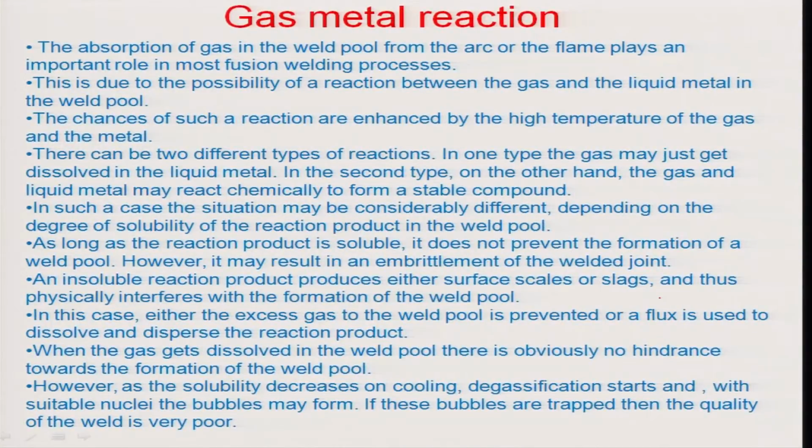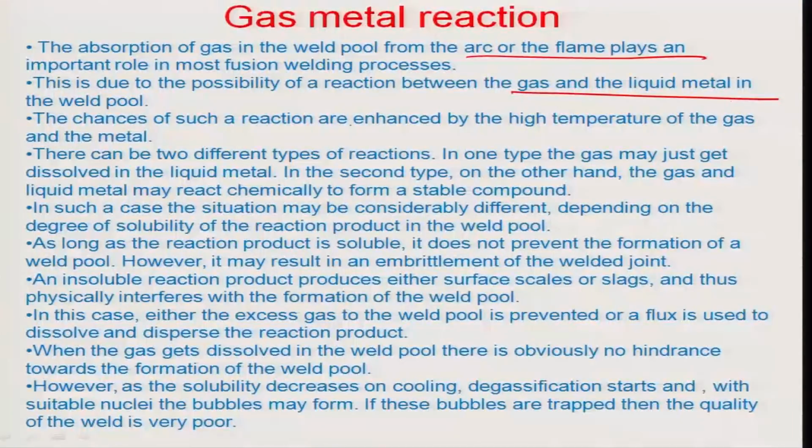So, let us also focus on the gas metal reaction, what happens. The absorption of gas in the weld pool from the arc or the flame plays an important role, okay, in the fusion welding process. That is possibly true because of the gas metal reaction which may take place in the weld pool, and chances of such reactions are enhanced by high temperature of the gas and the metal, because obviously both of them have temperature which can suffice for that threshold energy or peak energy beyond which the reaction can take place.